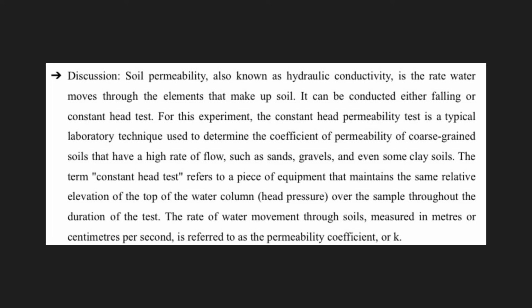The term constant head test refers to a piece of equipment that maintains the same relative elevation of the top of the water column, which is head pressure, over the sample throughout the duration of the test. The rate of water movement through soils, measured in meters or centimeters per second, is referred to as the permeability coefficient, or K.